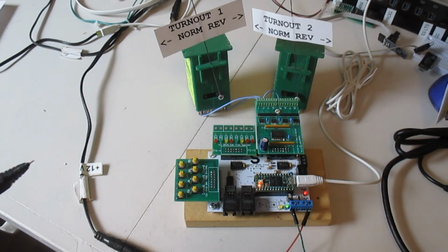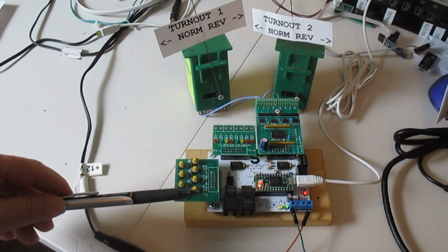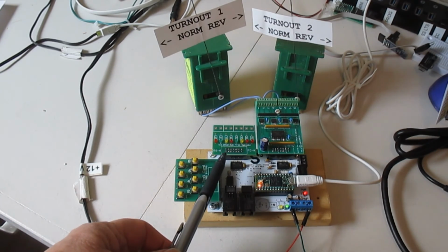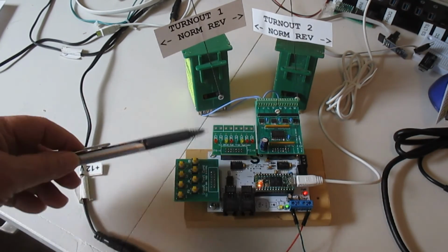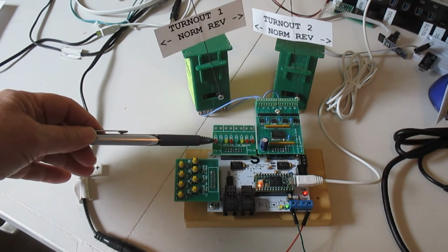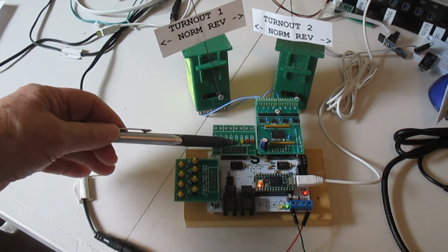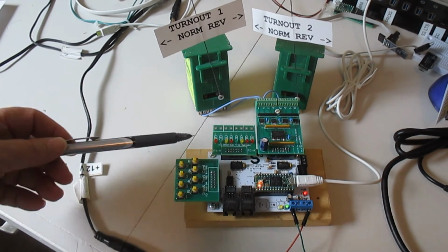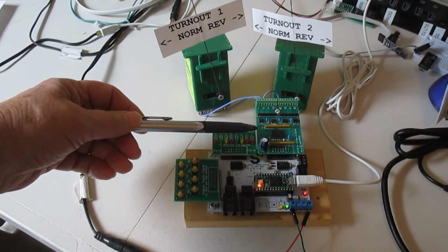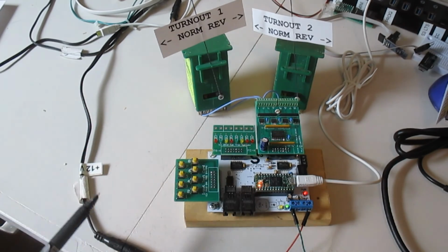In case you were wondering about the headers that are on the board, as you can see, we have a 14-pin header here. The reason is each of these headers carries both 12 volt power, regulated 5 volt power, and ground circuit, so that boards like this one can be plugged in and can be operated directly from the power of the board that they're plugged into.